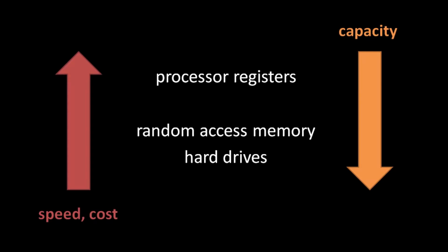Even though RAM is much faster than hard drives and other non-volatile storage, RAM is still relatively slow compared to the operations of the CPU. Therefore, another level of storage is used in between the processor registers and RAM, called the CPU cache. This cache uses a form of memory called SRAM, short for static RAM, as opposed to the DRAM, dynamic RAM, used for system memory. Unlike DRAM, SRAM doesn't require a refresh cycle to keep its content, allowing SRAM to be read and written significantly faster. Moreover, the processor cache is often placed on the CPU die itself, allowing for faster access by the CPU.